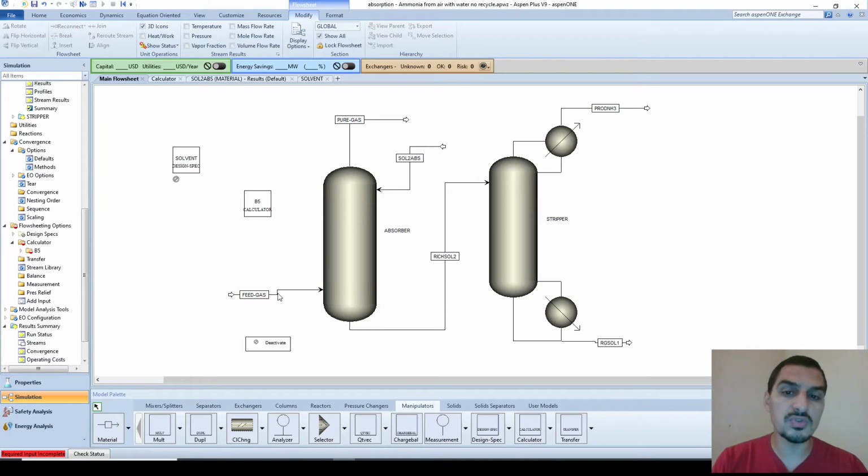So this is the minimum, which will achieve no mass transfer. So we use like 1.2 times the minimum, so that we can have a reasonable number of stages to achieve what we want to achieve. So what I'm going to do now is to calculate the solvent flow rate from the feed flow rate, so that it's 1.2 times the feed flow rate. Let's say this is what we're going to do.